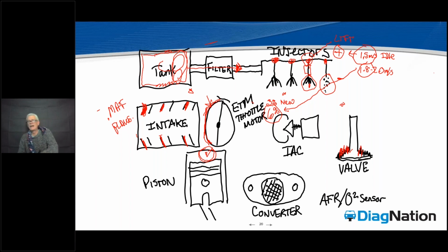If I'm working on a GM car, I'm going to have high pulse width. Now here's the technical argument that gets your mind into how to look for, cure, and know you've cured, to the best of your ability, a poor fuel mileage complaint. There's no OBD2 code that says vehicle using too much fuel, please check and advise.